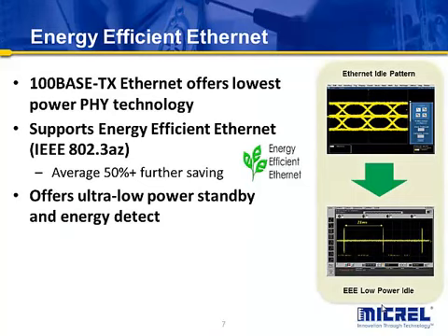100BASE-TX standard Ethernet already offers the lowest power technology. Compared to gigabit technology solutions, power and cost are reduced up to threefold. Further enhancements in energy efficiency can be realized with IEEE 802.3az energy efficient Ethernet support, where during idle periods, i.e. when no traffic is being sent, the PHY can fall back into a low power sleep mode, reducing power consumption by over 50%.